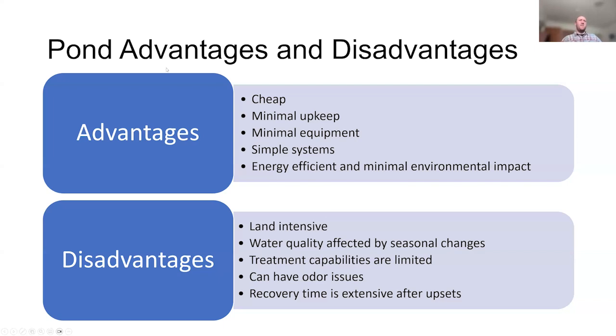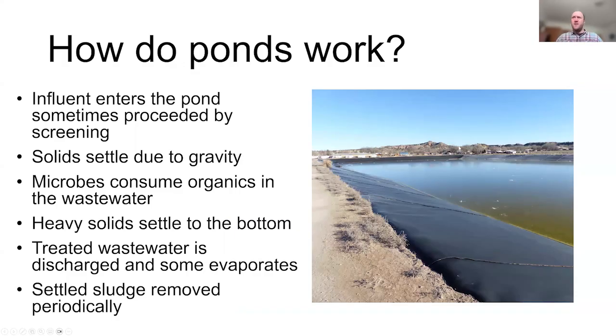Okay, and then so how do they work? This is actually the same lagoon, just a different angle from it. So wastewater is coming in from this community over here. It flows down, and actually this community has a lift station that pumps the wastewater into the lagoon. And then the solids settle out due to gravity as they come in because it's a very slow moving body of water. So everything settles out, or everything that can settle out will. And the microbes consume the organic content in that wastewater.